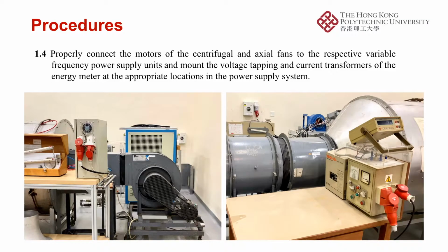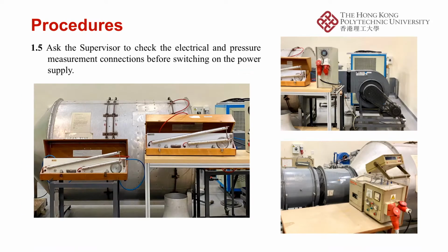Properly connect the motors of the centrifugal and axial fans to their frequency power supply units, and mount the electrical energy meter. The last step in stage 1, ask the supervisor to check the electrical and pressure measurement connections before switching on the power supply.